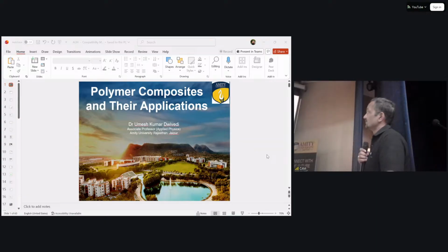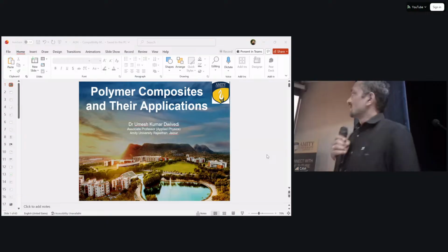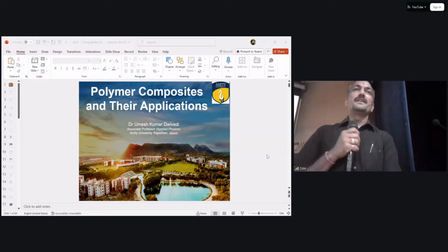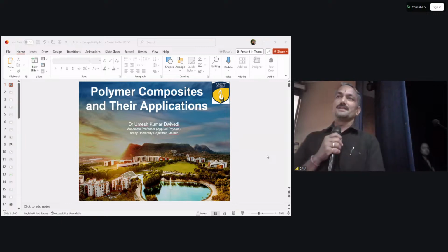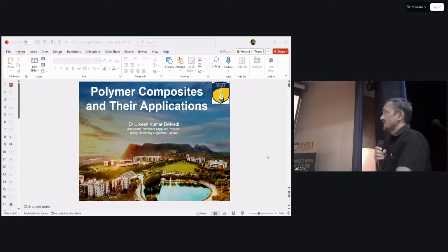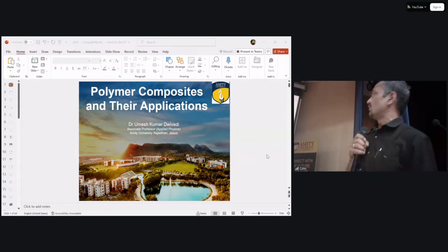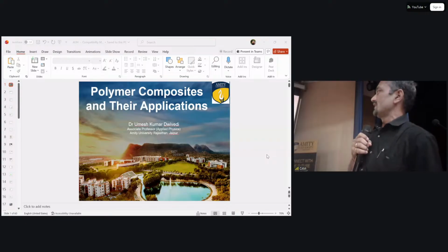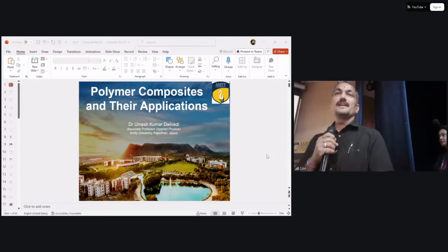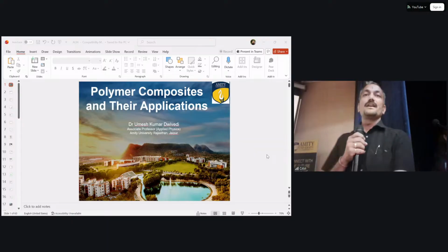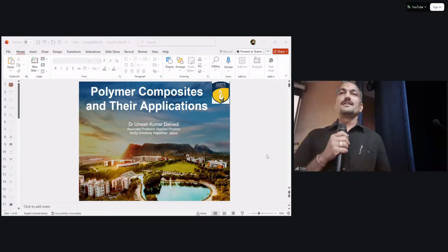Here you can see the new generation of LPG cylinder. It is already in market. Go Gas is supplying this cylinder, and that heavy cylinder is now being replaced by this polymer composite material. It is a seamless composite translucent cylinder made up of a polyethylene molded inner lining, glass fiber, and resin, with the inner liner creating even greater strength, and an outer layer makes this a perfect one to use. So this is already in market. You can see how the technology is being shifted here. Now the metallic cylinder is replaced by fiber composite material.